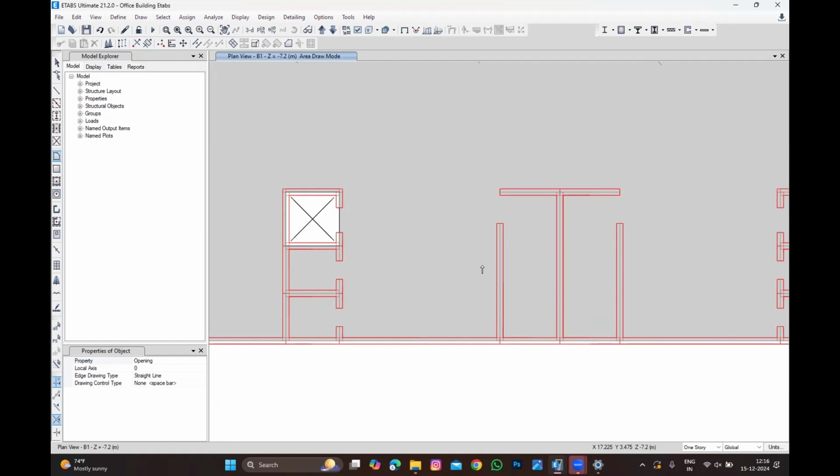In per floor, you'll have mid landing, right? So two flights actually. In per floor, if you're just looking at it, you will have two waist slabs, right? Then one slab completely, entire as one slab actually. Okay. So don't leave as an opening. If you leave as an opening, the wall will lead to more reinforcement because there is no connectivity on this side. Stair will give you supports. Yeah. Stair will give you stiffness. Stair will give you support.